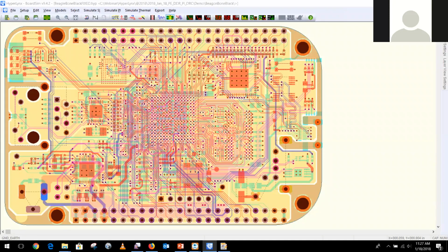The other approach is top down. Top down is what ERC is. So here's my whole board, just go through everything for me. But the problem with running top down is you may have lots of errors that are not true. For example, you may have an LED signal crossing the gap. Who cares? It's okay. LED line's fine. Resistor pull up, pull down. So you have to filter those kinds of things.